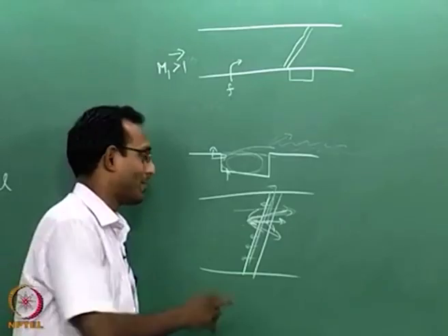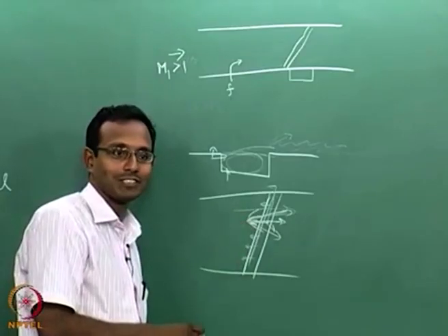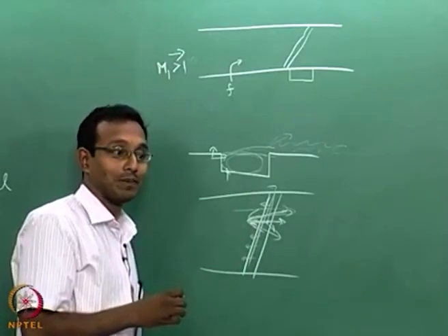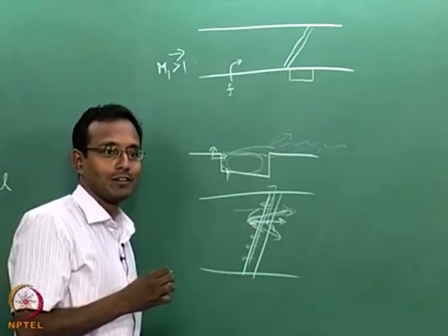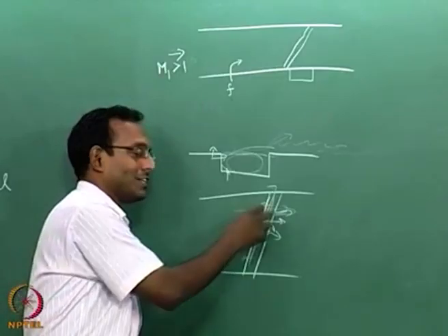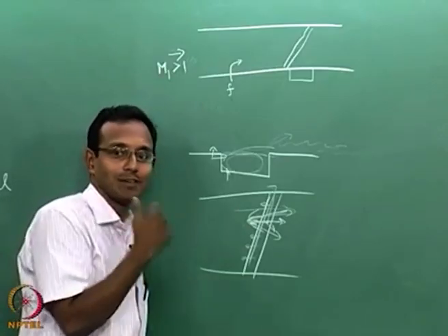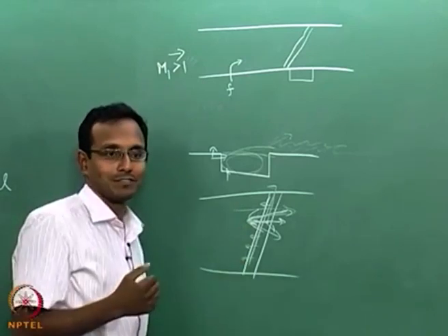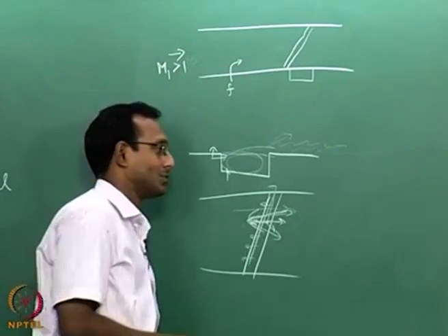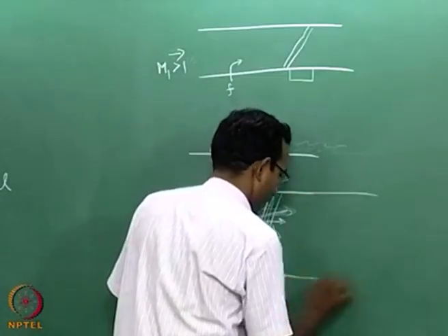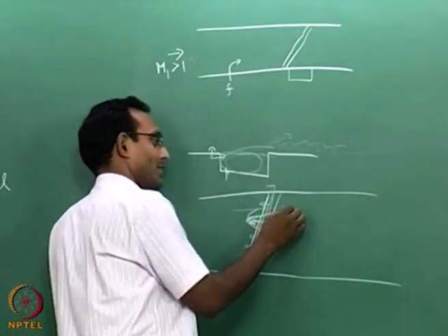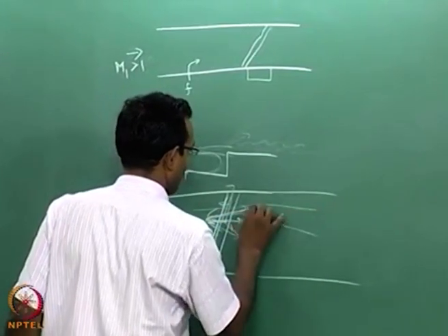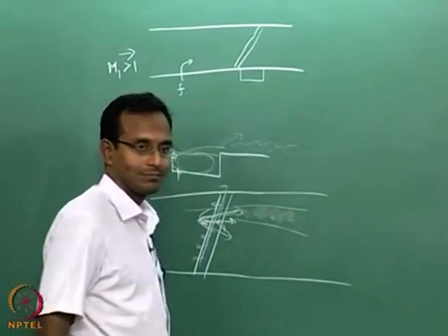Now that is not enough. I have decreased P naught, I have put shocks inside, I have put a metal rod in the middle, injected fuel, mixing, everything decreases P naught, and so I am going to have lesser P naught, which is again pushing towards M equal to 1. In all this, I want to light this mixture and burn it. So I am going to light it, and as it is traveling, I want it to burn inside here.